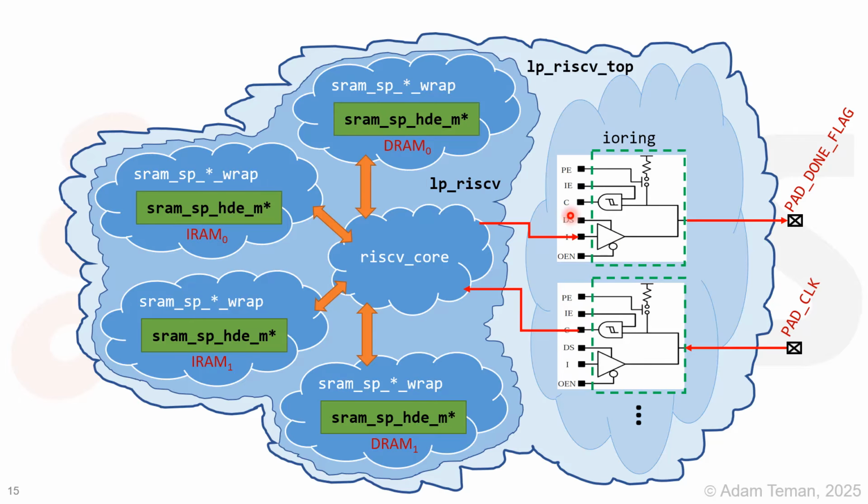And so just as a higher level now of what we have in our entire SoC over here, we have our RISC-V core over here. Okay, and it's connected to the data wrappers, and there are 2 of these data wrappers of 16K, which instantiate the actual 16K cuts inside. There are 2 of these wrappers of the instruction, the 16K instructions, or there could be more. Again, this depends on how you make it, with instantiations of the actual SRAM block inside.